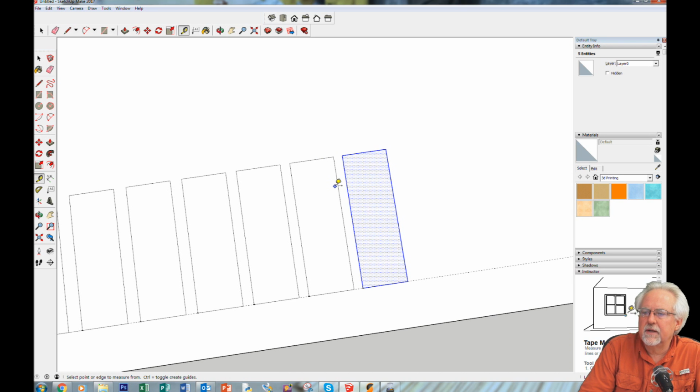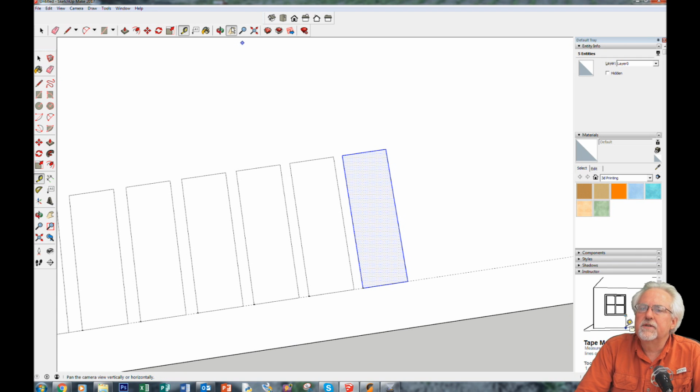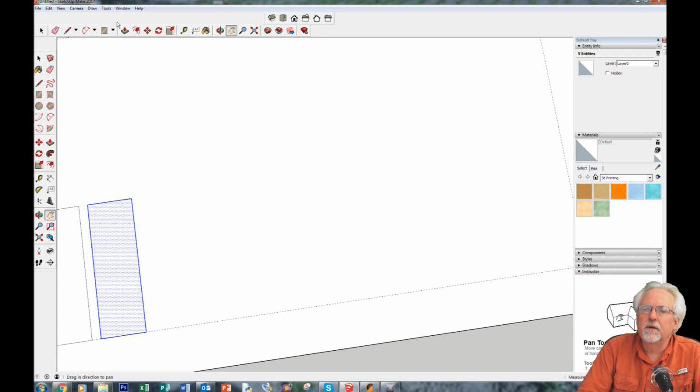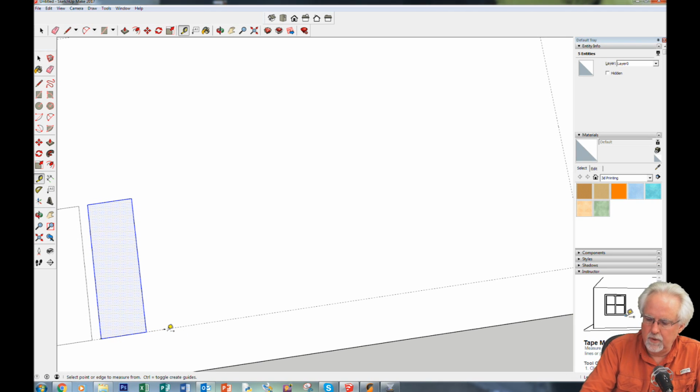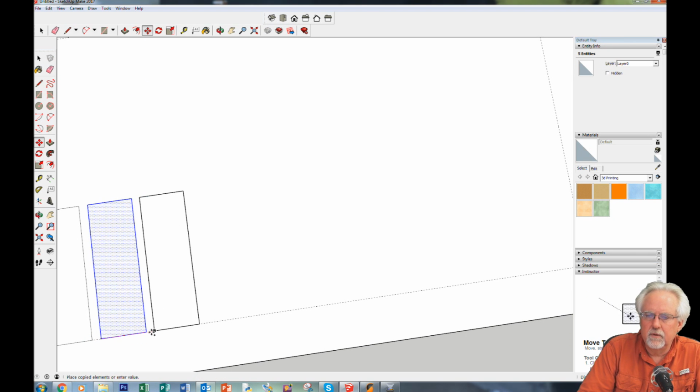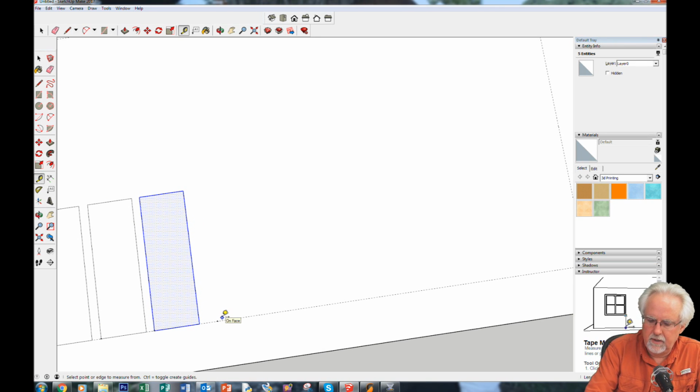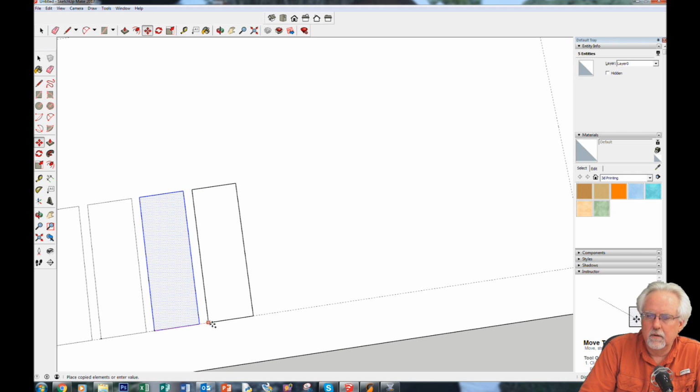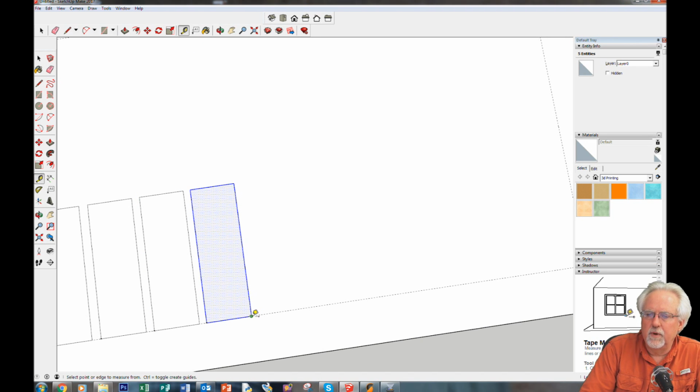Okay, let's check that, make sure that we are, yeah, we're doing good. So that's 1. I'm going to move this over. We're halfway through now. We're going to go down to 0.9. Get the ruler, snap to the corner, come out, 0.9, enter, move tool, tap Control, 0.9, 0.8, okay, we're going to do 0.7, 0.7, enter.